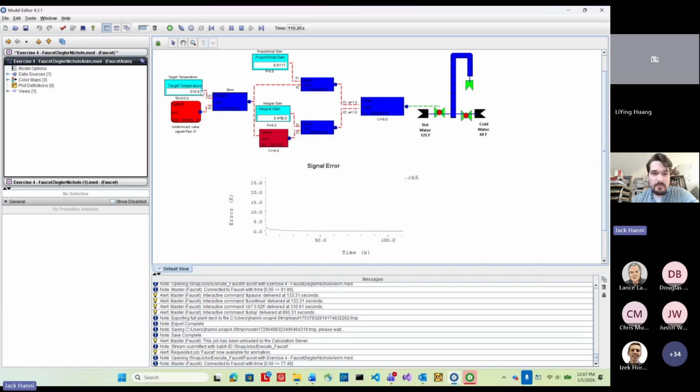And actually, I have on the exercise that you can change the target temperature, but you'll note that the integral doesn't naturally reset when you change the target temperature, which is a problem, because then your response is offset by an integral. Say you're messing around with different proportional gains and your integral was really large because it had been off from 0 for quite some time, say 3000.